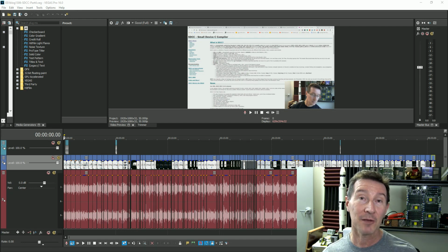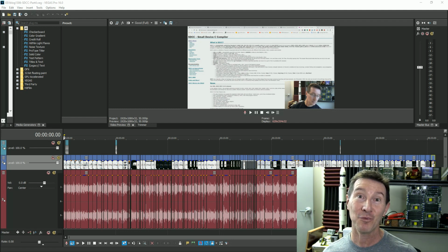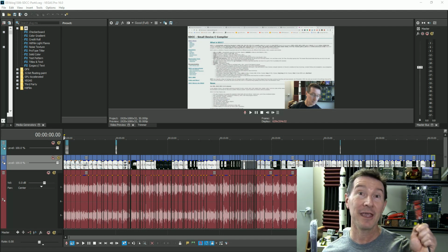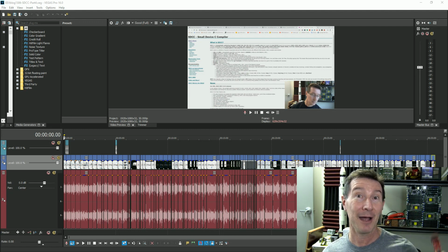So this video is actually going to be about using the SDCC, or the small device C compiler. And this is a compiler that supports the Padauk microcontrollers. A lot of people on the EEVblog forum actually worked very hard to get all this stuff working. So we now have a proper ANSI C compiler that supports the Padauk. So can we actually use this SDCC to compile a program for one of these Padauk microcontrollers, so that we can generate an Intel hex file to use in the next part with the programmer hardware to program it? Sounds easy, but as usual, there are lots of hoops to jump through.